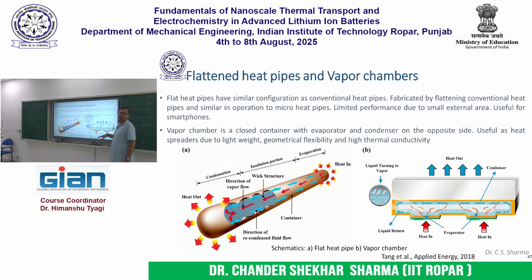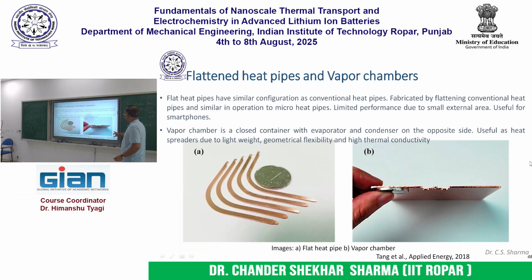So here we come across another counterpart of the heat pipe. It is called the vapor chamber. So a vapor chamber is the same as the heat pipe. The only difference is that in the heat pipe, the evaporator and the condenser were separated by a certain distance. In the case of a vapor chamber, the evaporator and the condenser are directly facing each other, and this vapor chamber can then dissipate heat in the z direction. And in some of the smartphones now, this configuration of vapor chambers is being implemented.